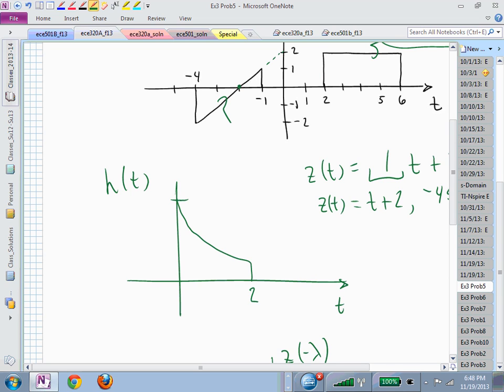But on this question that I've added to, I said, okay, let's have this for the impulse response, h of t. So I want my function that I'm flipping and sliding, at least its rightmost endpoint, to be to the left of wherever this one starts. And so I slid it over to the left of the vertical axis.